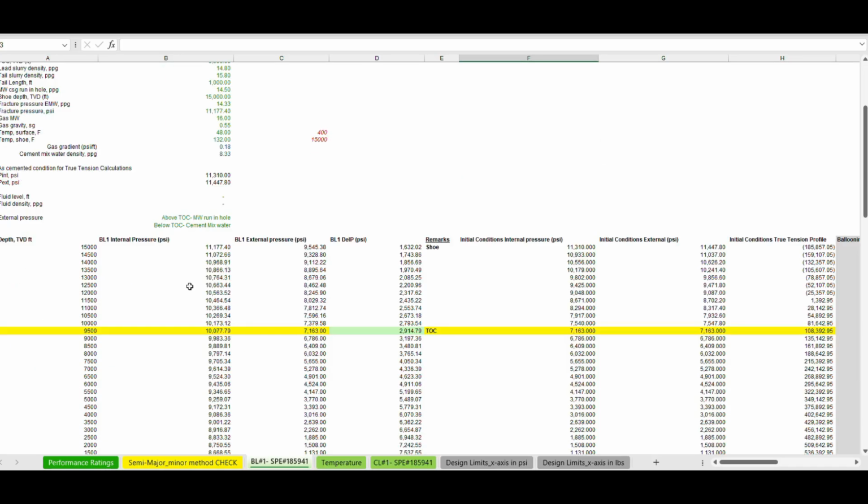So how I calculate it, now I'm going to show that one. In part number 3, we set that the final tension profile of the casing is calculated from the initial condition states up to the final state by taking into consideration the ballooning, temperature effects, drag, any bending, and the shock load.